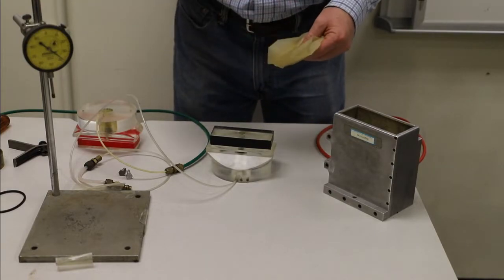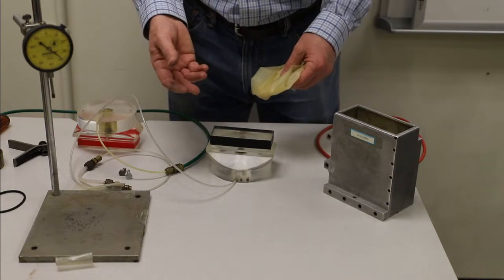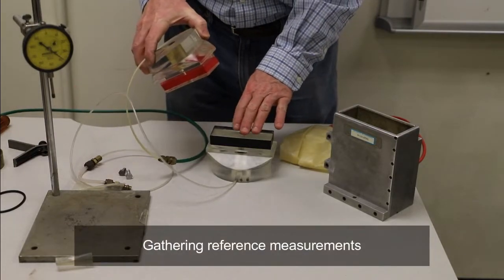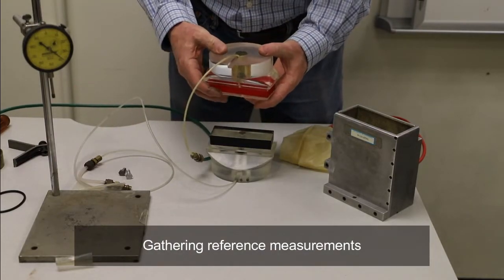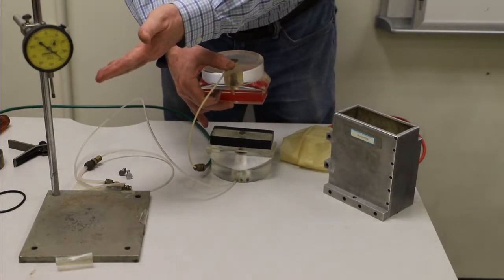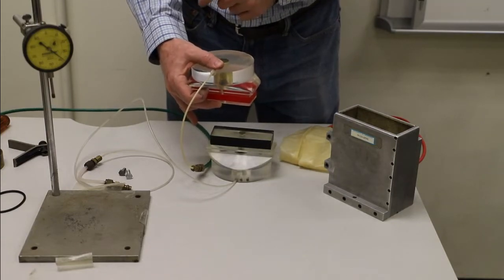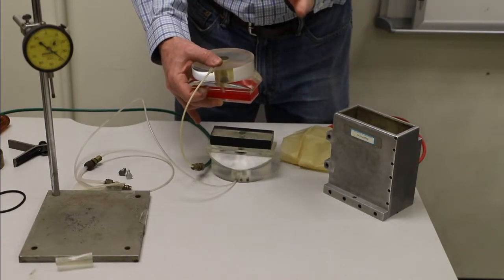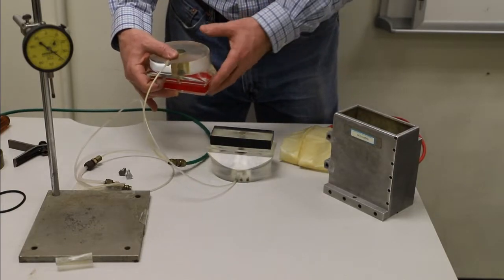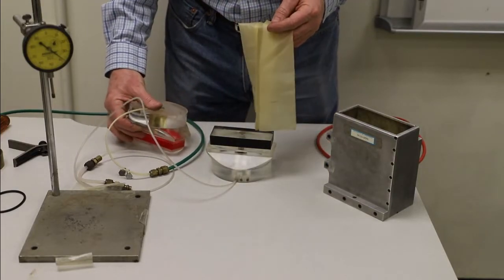Now the process is very similar to building the reconstituted triaxial sand specimen, in that we would normally start by having a reference height or a reference block in there of a known height, putting the system together, measuring under the dial gauge what the reference reading is, so that once we have a soil specimen in there we can compare it to know what the initial height is very precisely. And also we would want to measure the thickness of the membrane in the same way.